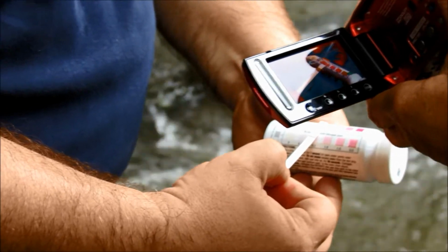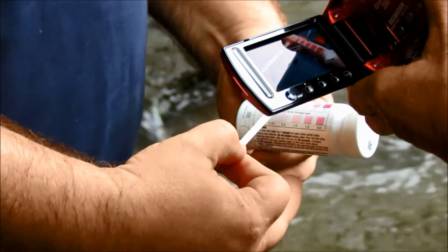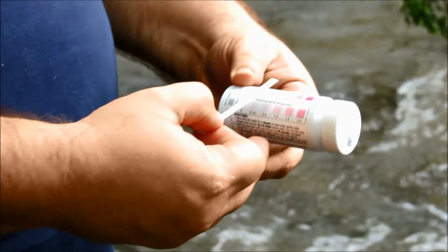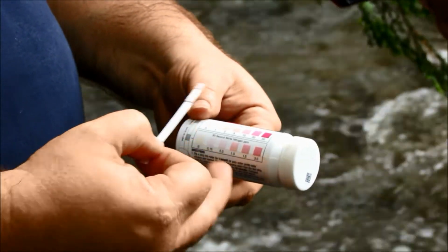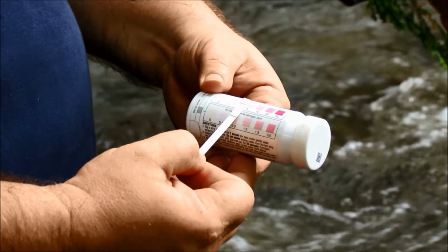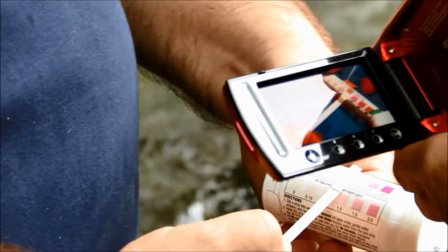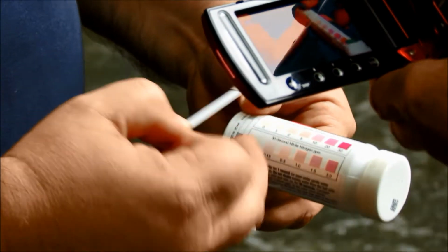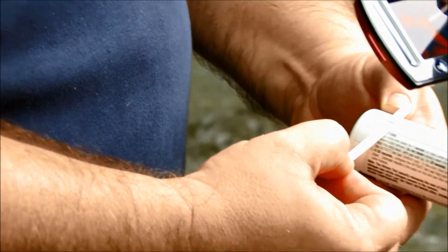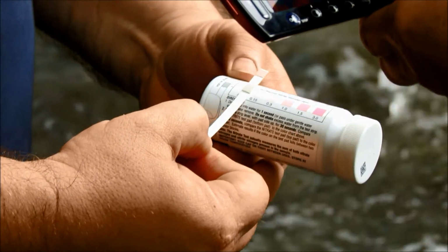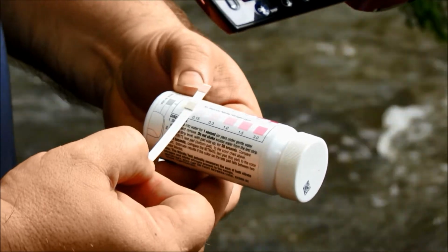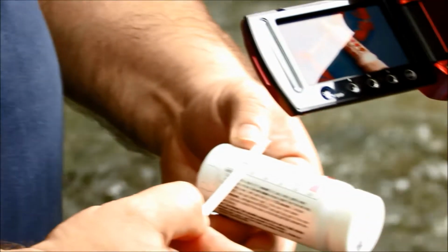Not a great value, but typically, if this was a water well, you would say, hey, this is a water sample we should take to the lab. This is very typical after a rain event for a stream. If you came here during normal flow, your nitrate levels would be down here. It also tests for nitrite, the reduced form, and that's very low. Nitrite is the more toxic of the two.